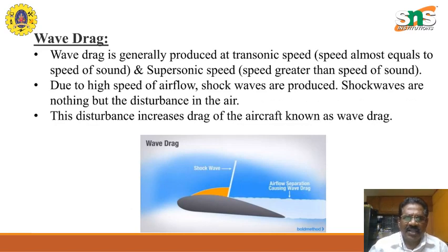Wave drag is generally produced at transonic speed, which is almost equivalent to the speed of sound, and at supersonic speed. Supersonic speed is the speed greater than the speed of sound. Due to the high speed of airflow, shock waves are produced. Such shock waves are nothing but disturbance to the air, and this disturbance increases the drag of the aircraft, which is also known as the wave drag.